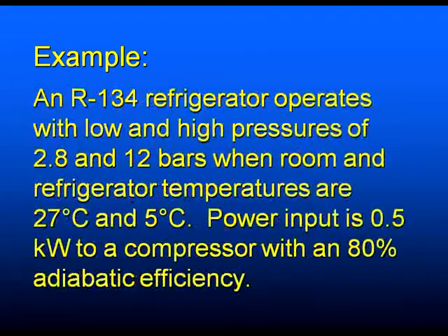Let's take an example. We have R134a, I should say, as the working fluid, and it operates with low and high pressures of 2.8 and 12 bars. Now, on a standard refrigeration cycle, you would see this would be called the suction pressure, and this would be called the discharge pressure.